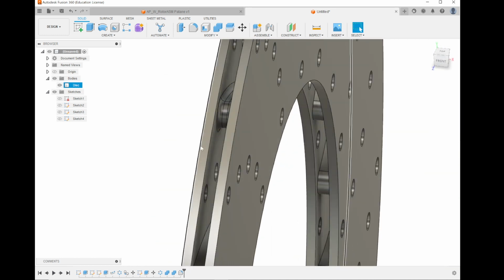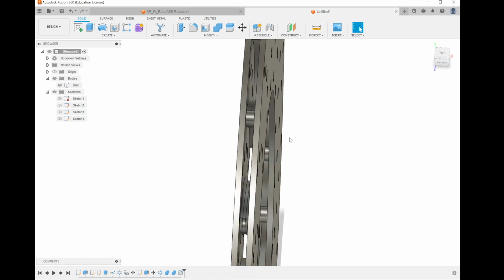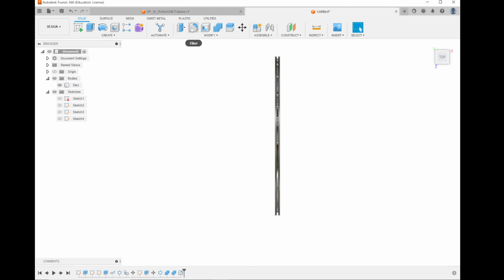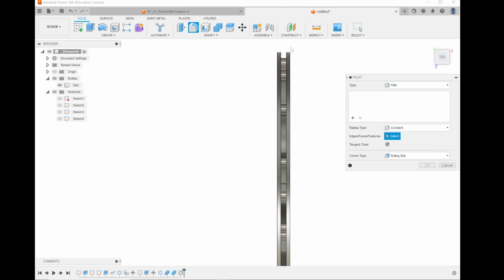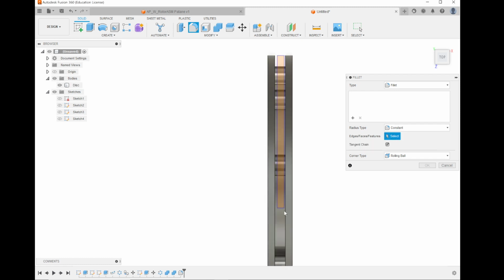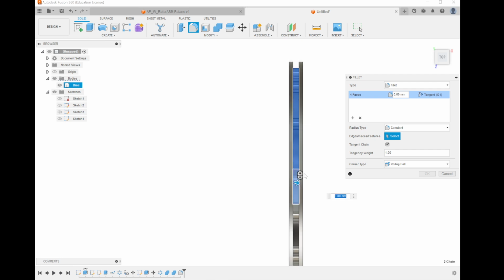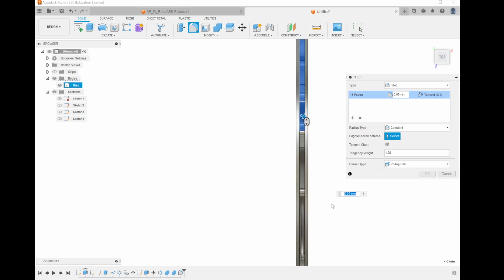For the sake of consistency, you should do this with all the parts, but I'm not going to show you that on the video. I don't necessarily know if there's a fast... There might be a fast way to do it, actually. If I do this view over here in the top, and then I go to Filleting Tool, and then for the edges and features, if I just press this now... you just got to go through and click them all.